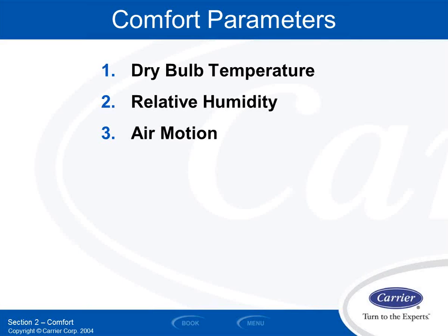That airflow comes across your body and takes the heat and removes it from your body and puts it somewhere else behind your body, right? So that airflow can help cool you off. Likewise, if someone's already cool and cold and there's too much air motion, they'll complain about drafts and stuff like that. So having the appropriate amount of air motion in the space to either blow directly on occupants or not does have an effect. Additionally, in many types of systems like overhead heating and cooling systems in an office building, we need to have the air motion in order to get the air changes in the room.